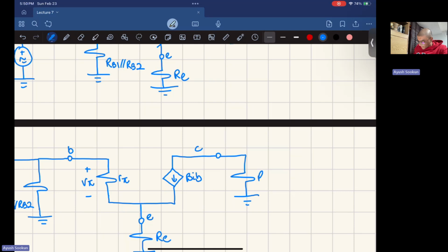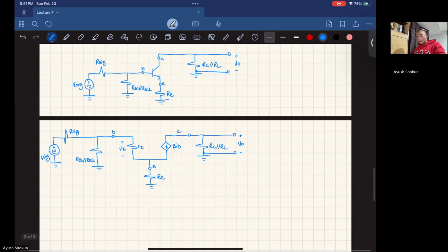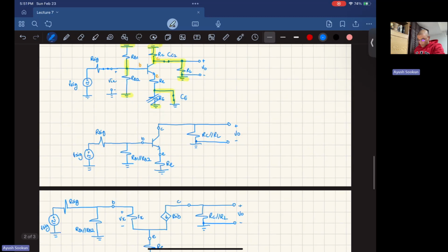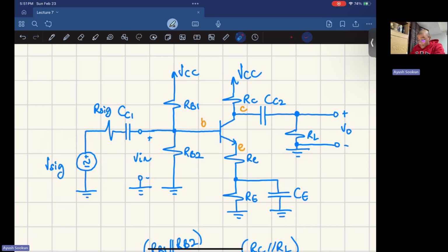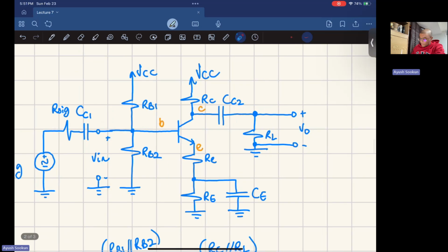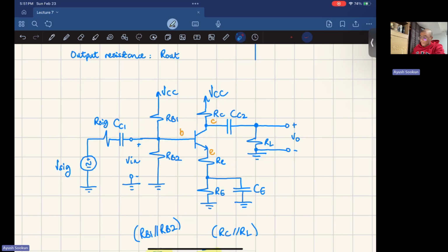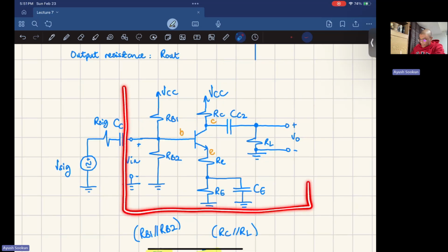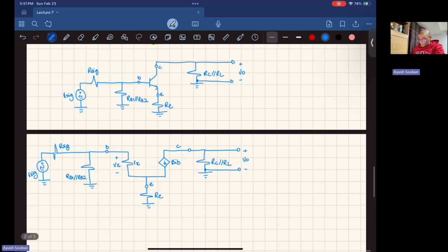Now, there are multiple ways to find the gain of the circuit. I'm just going to show you a methodology that works for me, and if you follow it and practice with the same methodology, it's a step-by-step process for you to be able to find your gain. Okay. So now if I go up a little bit, I will notice that in the circuit here, this is V sig, and then this is V input. So if I want to find V out over V in, it's this voltage that I need to consider. I need to find the ratio between this one and this one. So I can completely ignore this part temporarily because the only part of consideration of the circuit is this box right here. V out over V in, that's what I'm trying to find. So this is what I'll do.